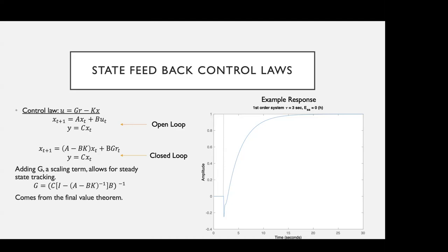But if you did a Kalman filter, instead of this L, you would have K, which is your Kalman filter gain. It's a Gaussian estimation of your output data, and you assume some statistical properties of that output, and then you use that to inform how to feed this back and minimize the error between the two. Is this Kalman filter spelled KALMAN? Yes. So I guess your question is, do I need to have that band? I don't think you need to have a band because you would just use Kalman filtering and control directly.